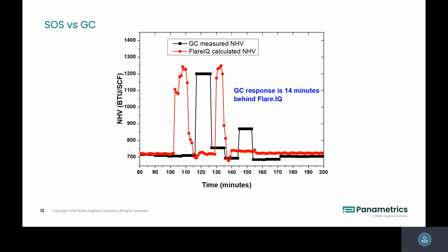But the main takeaway, which especially the control engineer knows, is that GC has latency: 10 minutes, 8 minutes, 14 minutes, whatever, depending on your system. According to the regulation, you cannot have more than 5 minutes of smoke in a 2 hour period. But if your GC is 10 or 15 minutes slow in response, then you already have a 15 minute smoking event. You cannot win unless people are watching it 24/7.